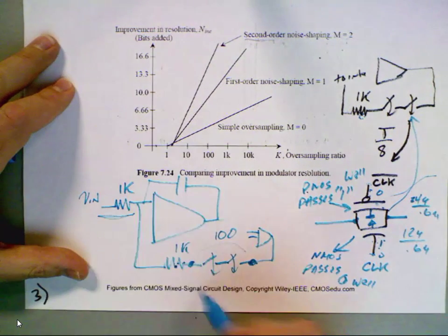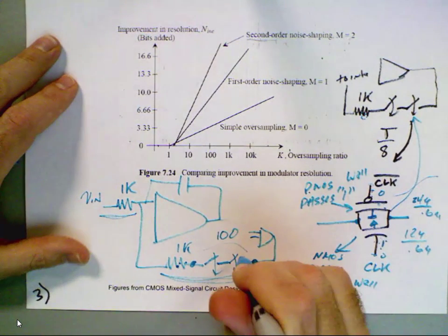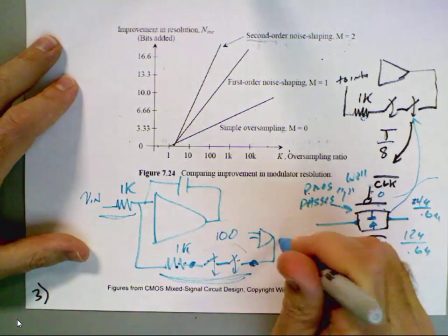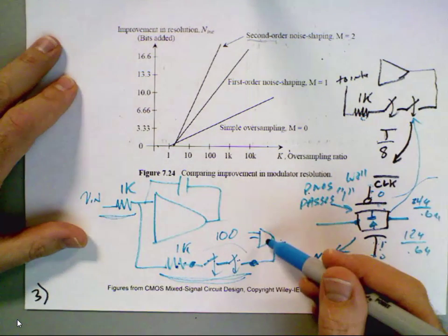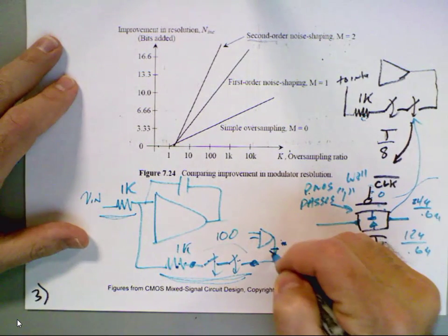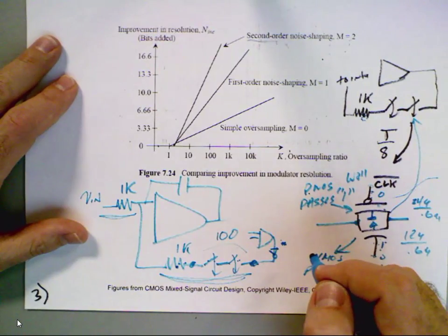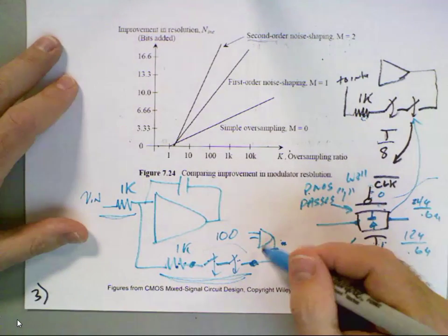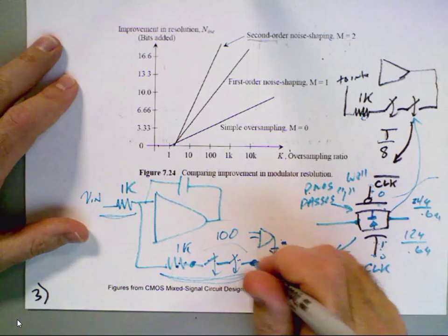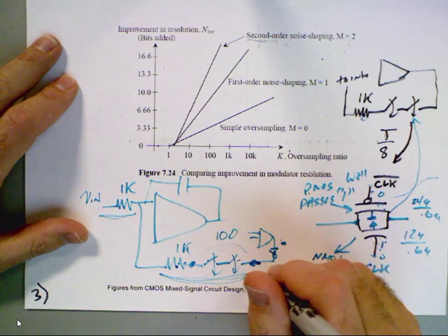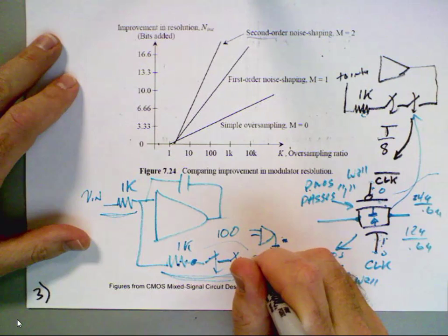So before I answer that, does everybody get the idea that putting the TGs here, and the finite drive coming out of your comparator, means you might have to put some inverters here? Remember, what did we do for the inverters in LTspice in our oscillator? Yeah, we used stronger ones, right? You may need to do that just to make sure this goes close to 0 and VDD. You don't waste time on this. You simulate it and you look and you decide, is it fast and is it going to 0 and VDD?